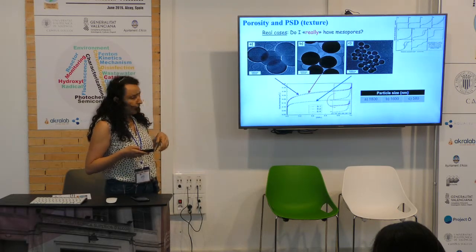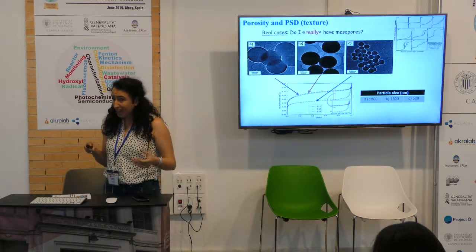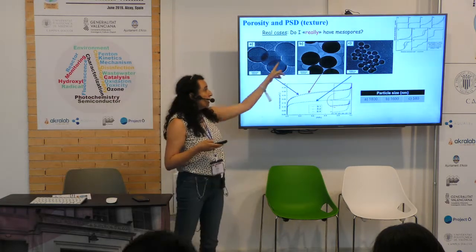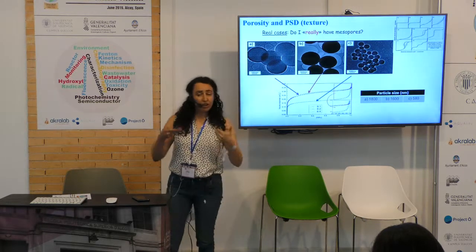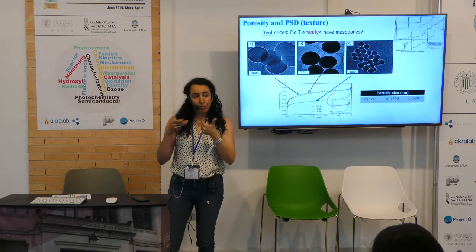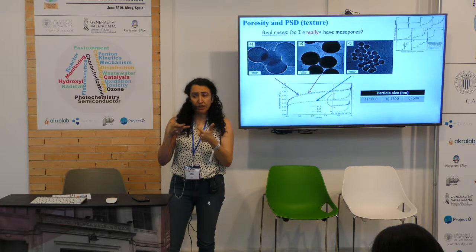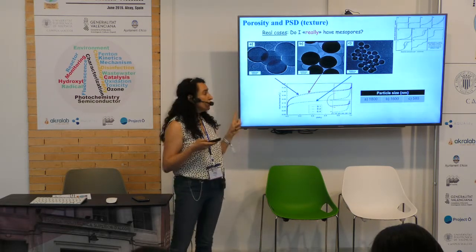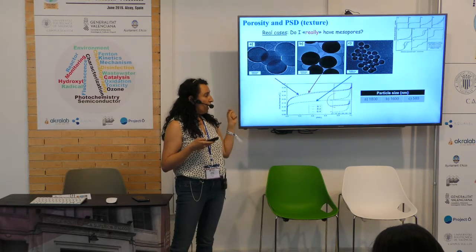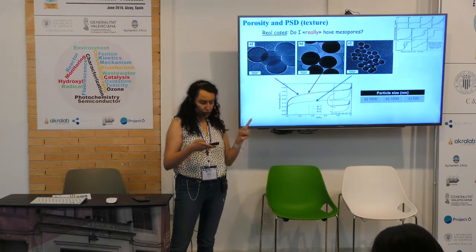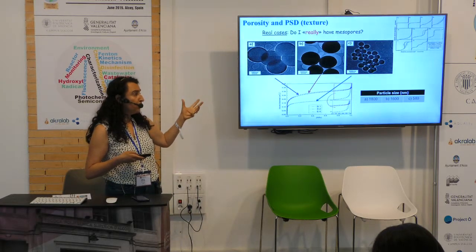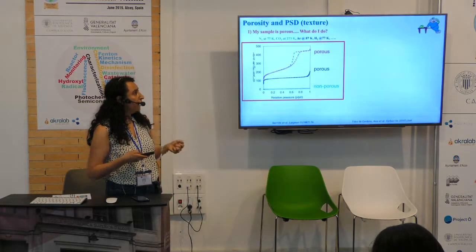Also, you can have an impact of your particle size. If they are spherical and very small, you can have artificial pores, which are actually just interparticle porosity and not inside the particle. You have to be careful, and this is why you also have to combine different techniques in order to have a complete view of your material.